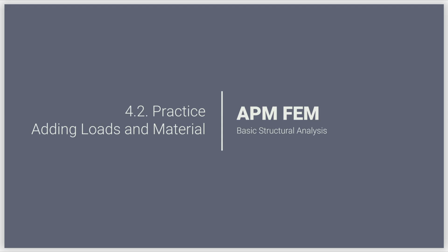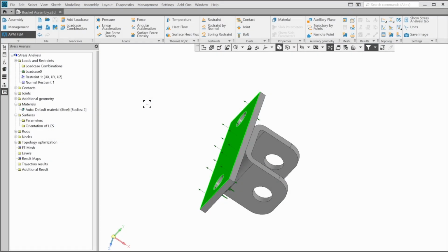In this lesson, we'll add loads to the assembly and learn more about how load cases work. Then we'll assign a material and learn how to modify its properties. As a load, we'll use a force that pulls on the bracket holes.